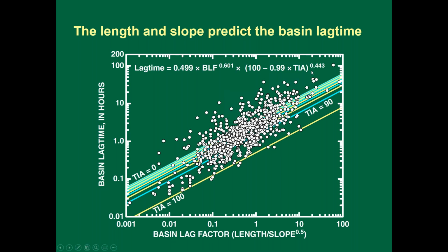And yes, the data for these 895 basins have a pretty good amount of scatter. That's to be expected for a nationwide data set. And again, when you look at SELDM, you can use professional judgment to vary the variables to get the basin lag factor that you expect if you have on-site data.